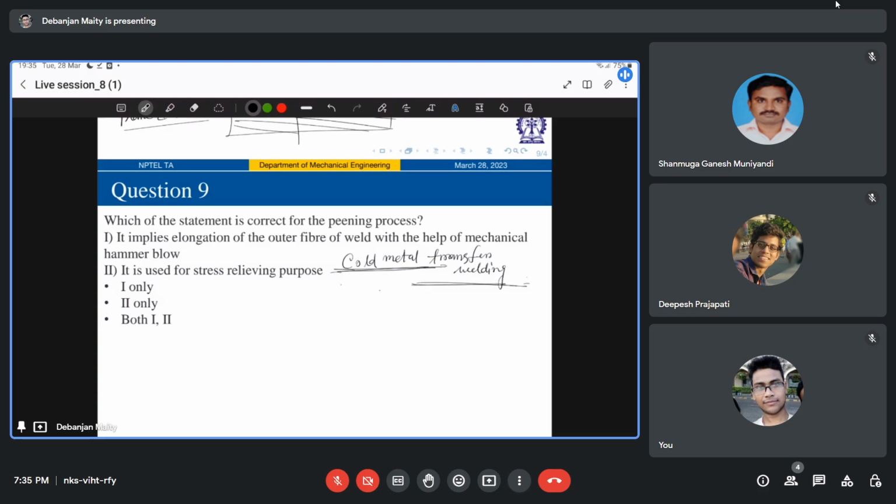As we are talking about heat treatment or thermal stress relief, heating lowers the yield strength of the base metal, and it allows localized relaxation of residual stress, primarily by some kind of plastic deformation, or maybe some creep. So the effect of time and temperature plays a big role in this residual stress thing.